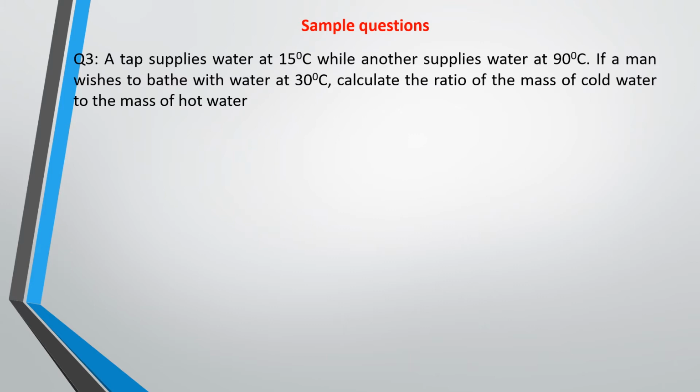What you should know when we talk about heat transfer or heat change by mixture, calculation of heat capacity by mixture, is that heat loss by hot water, let me represent that by QH so that I'll reduce writing, is equal to heat gain QC by cold water.